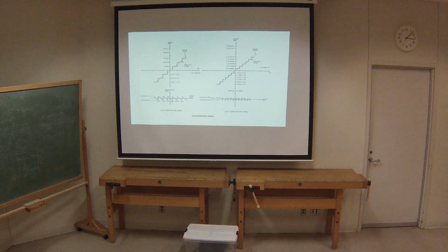Now, obviously, if we're talking audio, half a volt one way or the other just wouldn't cut it. But kind of what's interesting, remember the way you count in binary is 1, 2, 4, 8, 16, 32, 64, 128, 256, etc. Every time you add one bit, you double your resolution, right? So here, we're going to add one bit. Now, instead of having 4 bits, we have 5 bits.